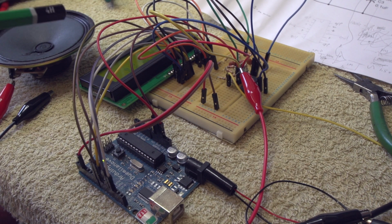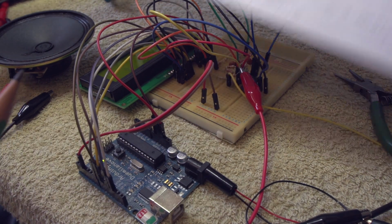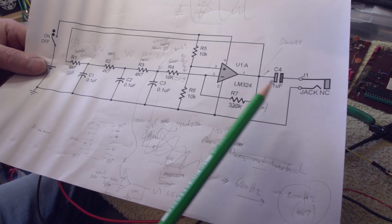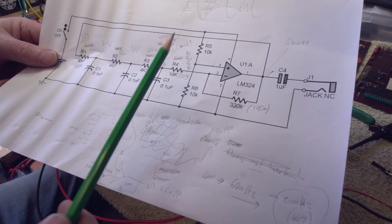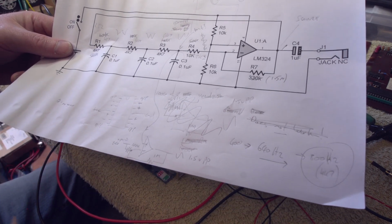What we want to concentrate on next is the side tone oscillator for the CW ident, and this typically is an audio sine wave that we need of around 800 Hertz or so. What I've done here is I found a bit of a lashed together schematic. It's a phase shift oscillator circuit, and using an LM324 forms this entire oscillator, and you do indeed get a reasonably clean sine wave output. It's not 100% perfect, but good enough for audio purposes.